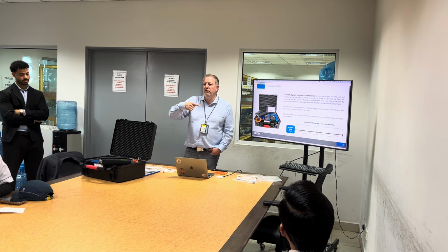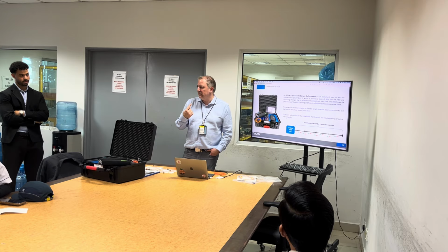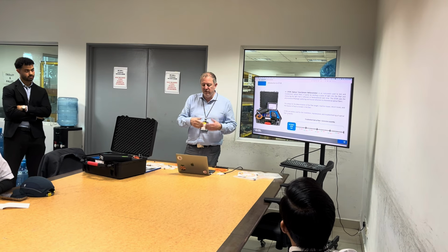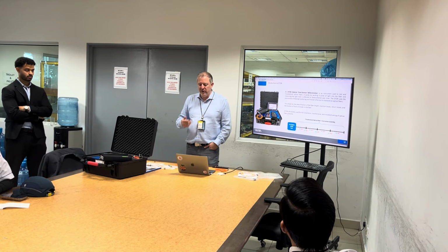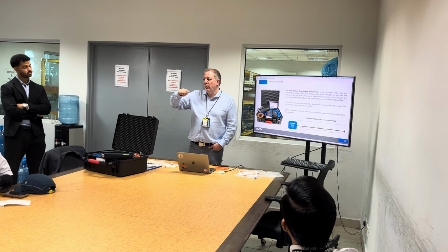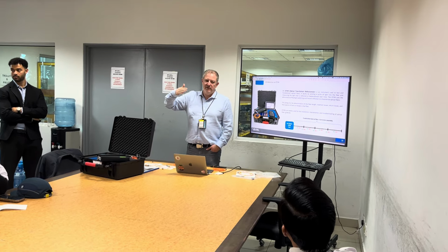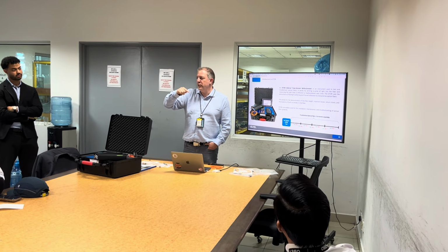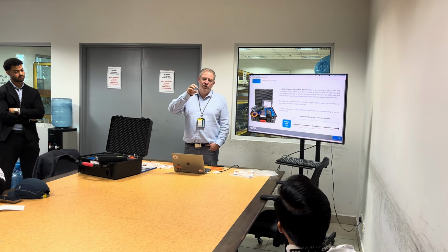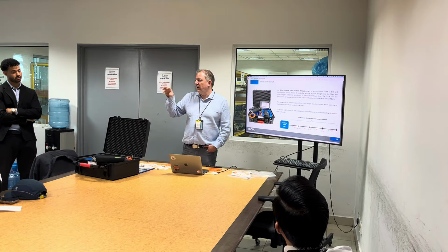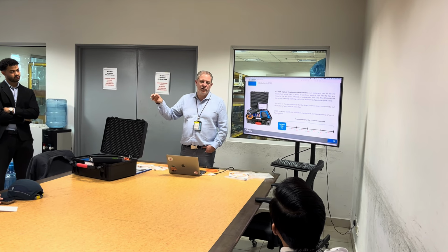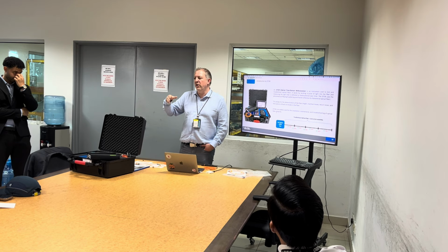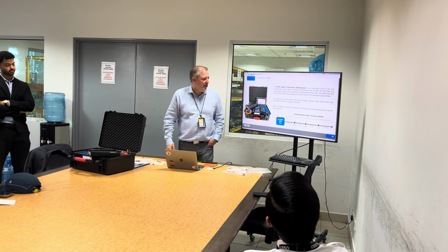So we're gonna scan the full fiber only from one end. That's a big advantage because you don't have to access both ends. You can check everything from one end, and we're gonna scan the whole link, and each time we see a connector or a fault, we're gonna measure insertion loss and give you the position of the fault or the connector and the insertion loss level, so you can figure out the performance of each event, whether it's a connector or a fault.